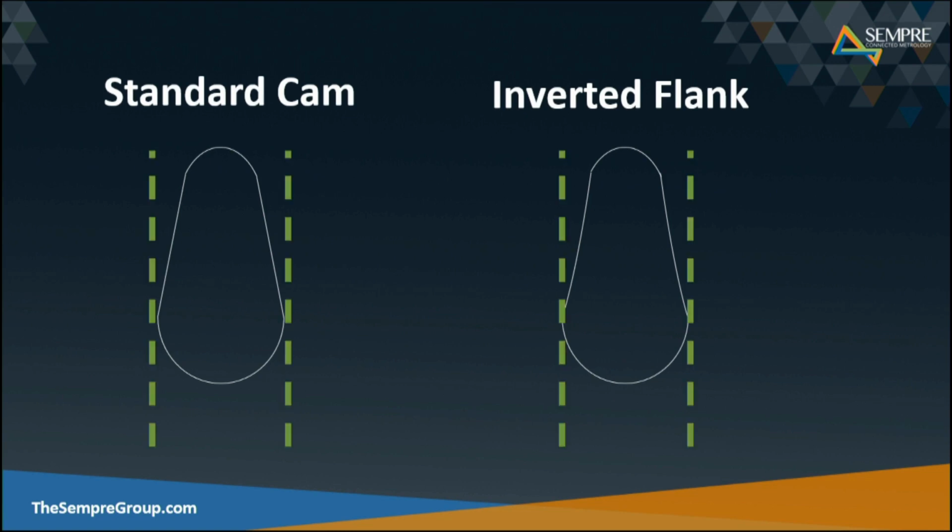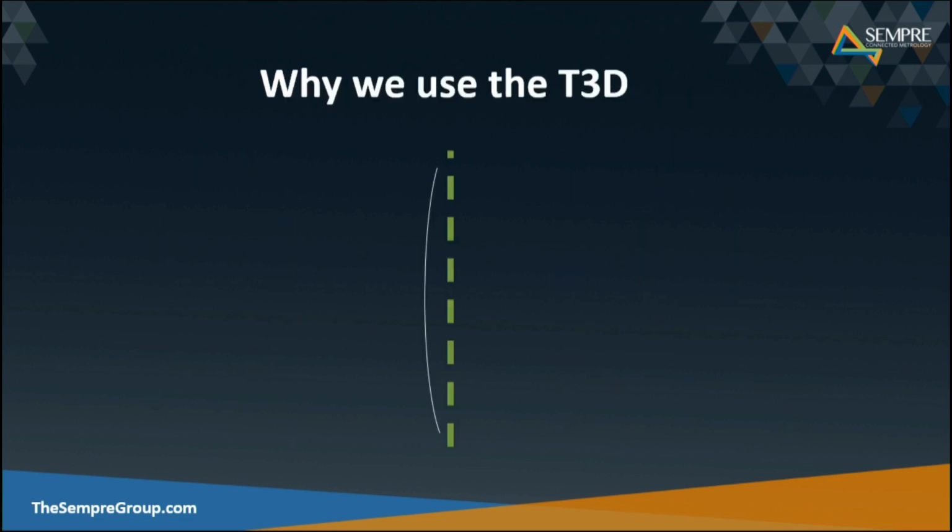So the difficulty we have when we're using an Opticline system is that when you look at the light that is passing through to measure those features, on a standard cam we don't have any issue because we're not interrupting the light source to look at a negative feature. If we were to zoom in onto the red circled area on the right hand side, you can see that we've got this effective inverted radius. Now where the light is, we've almost got an area where we won't actually obtain any measurement. So this is the same when you're looking at a length position.